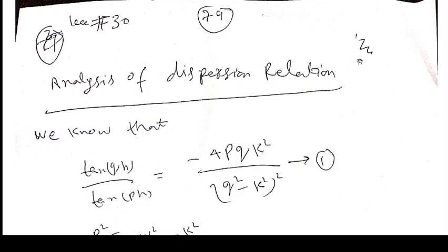All asymptotically approach CT, the transverse wave velocity, and only one mode crosses the line CT and approaches CR, the Rayleigh wave speed, and there is a plateau region in the spectrum of these modes.